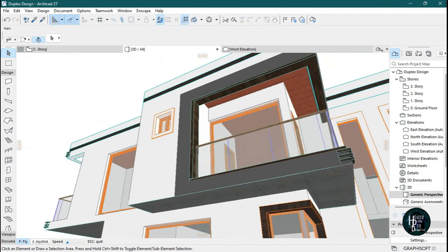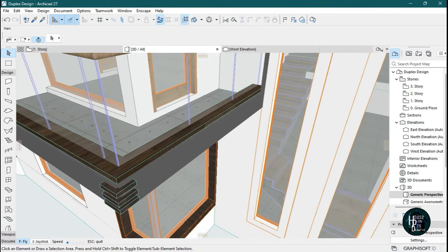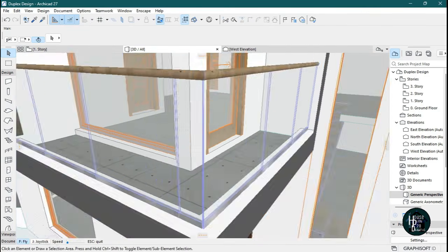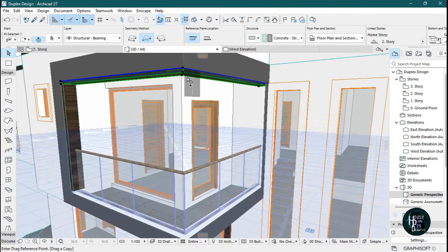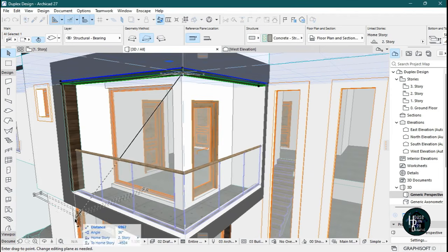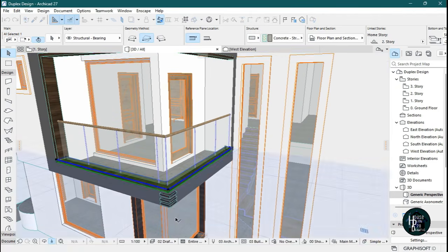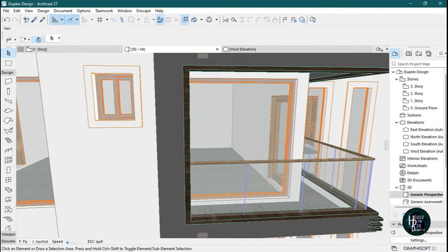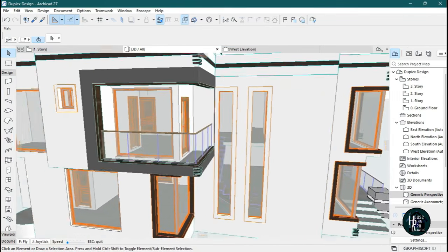I think this upper side is different from the downside. Okay, I think that's a mistake that's actually going on here. So I'm going to click this, I'm going to delete this. I'm going to make a copy of this. Press Ctrl Shift D, pick this point here and let's bring it down again. Okay, so we're going to have a perfect fit like that. I think this is what I'm actually looking for. Okay, so it intersects together. That's what I'm trying to look for.